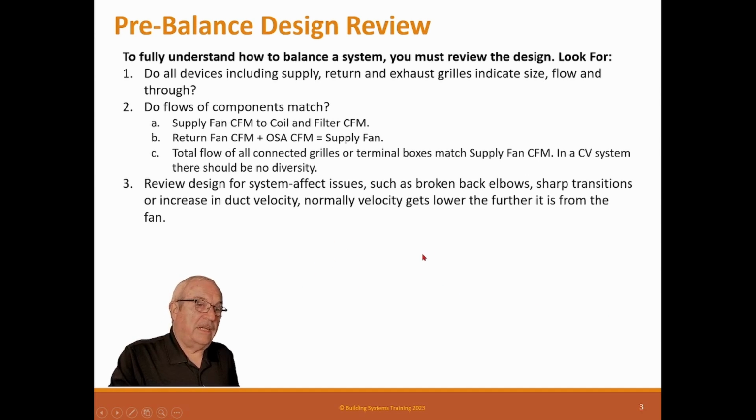So that's a typical thing, and the broken back fan just means that there's some things happening in the fan that's going to increase pressure a lot. And so we don't want that. Poor fittings that are not designed correctly will induce a lot of pressure, and that's a problem for us. And the reason the balance guys are concerned, that's an energy deal, right? Because to get flow, you may have to start jacking that fan up past its capacity because the engineer really didn't count on that pressure increase.